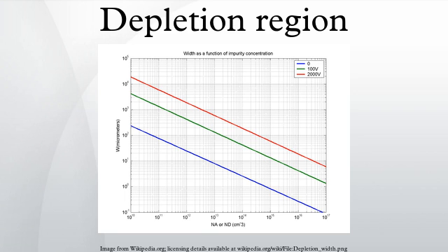2. Forward bias narrows the depletion region and lowers the barrier to carrier injection. The diffusion component of the current greatly increases and the drift component decreases. In this case the net current is rightward in the figure of the P-N junction. The carrier density is large, making the junction conductive and allowing a large forward current. The mathematical description of the current is provided by the Shockley diode equation. The low current conducted under reverse bias and the large current under forward bias is an example of rectification.